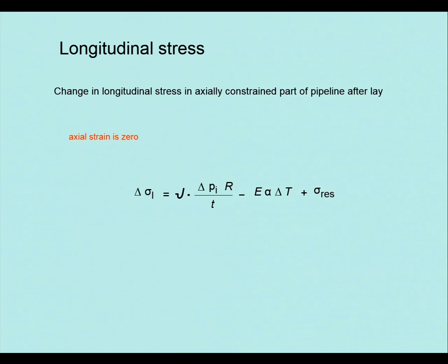This temperature, when you lay the pipe onto the seabed, it settles say at 4 degrees, or in some nice warm climates around the world, 14, 15 degrees, and then you heat it up to 100. That's your temperature difference. It's not the actual temperature of your product inside. It's the temperature difference between inside and outside.